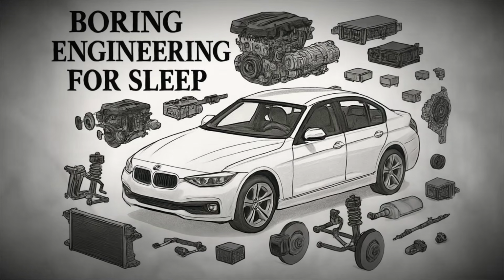Planetary gear sets, made of sun gears, planet gears, and ring gears, are arranged in combinations to create different gear ratios within a compact design. Modern automatic transmissions may have 6, 8, or even 10 gears to provide both smooth acceleration and efficient cruising.